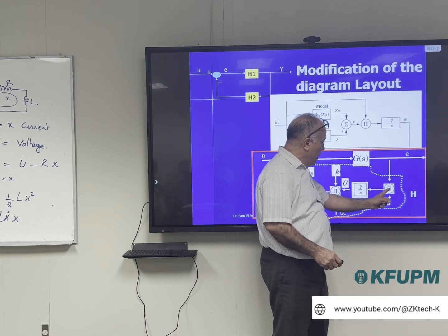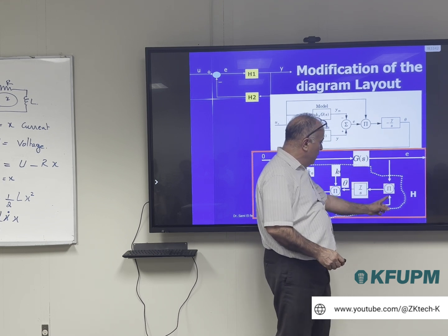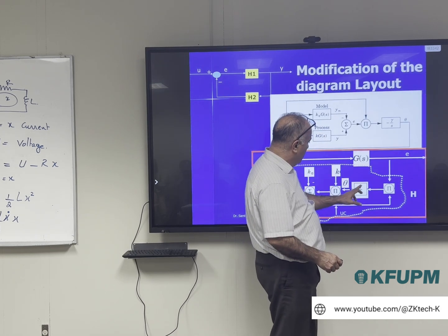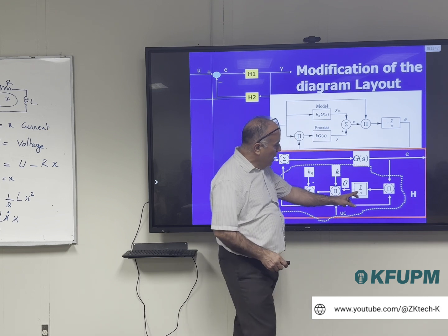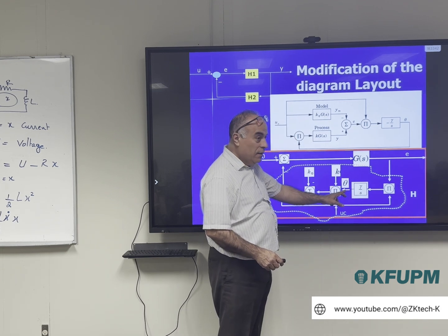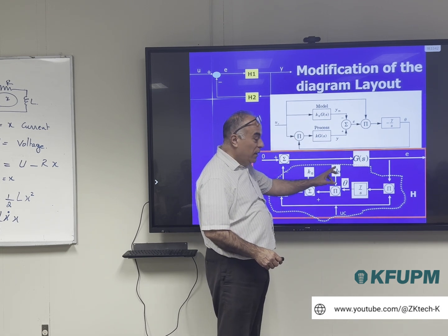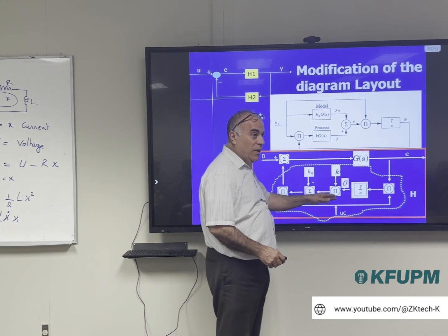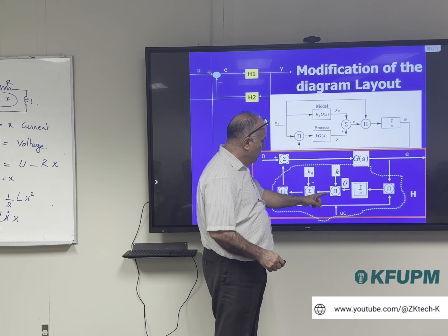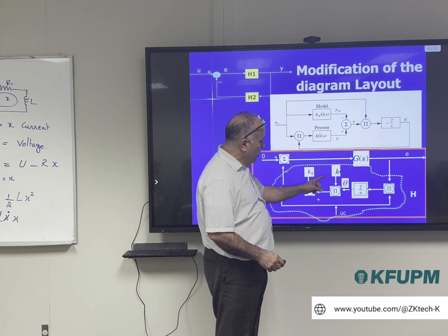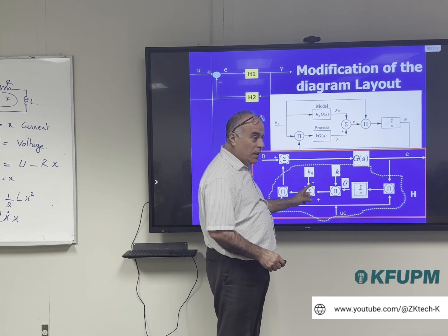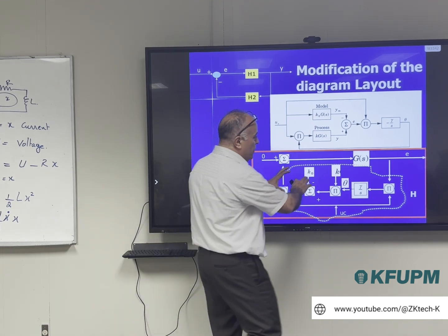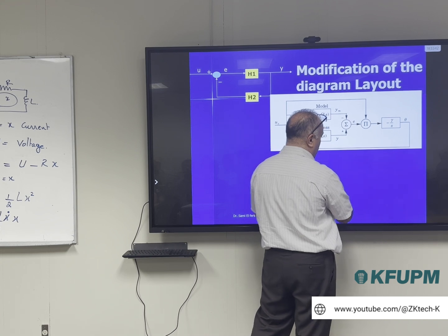And then this feedback, the error multiplied by UC, or multiplied by ym, multiplied by gamma over s. This will generate theta. Theta multiplied by K. K here is unknown, so we can put K in gamma if you want, but this is the general analysis. Then K minus K0 is the error between the gains, and all this comes back to the system. So all this block becomes for me H2.